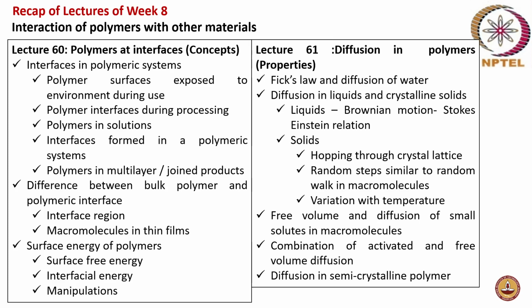Lecture 61 was on diffusion in polymers. The Fick's law, and then diffusion of water. Diffusion in liquids and crystalline solids were discussed. And then in liquids, the Brownian motion, the Stokes-Einstein relation, and in solids, the hopping through the crystal lattice for diffusion to take place.